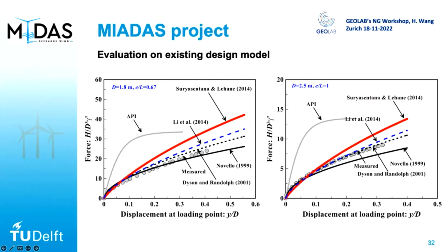it becomes kind of like a caisson. Then you have the contribution more from the base, from the shaft friction. And at that moment, we need to add further new components like this distributed spring and base spring. And based on some numerical simulation for monopiles in sand, even with an aspect ratio of 5 or 3, the contribution from all the other components is still around maybe 20 percent, or maybe a little bit more if the pile is really very large or the embedded length is really short.